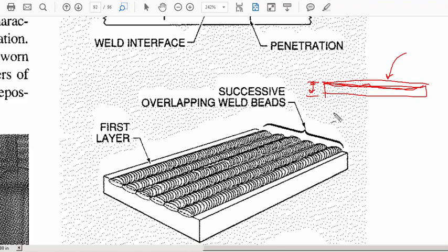This is obviously very abrasion resistant, so if you wanted your part to be well protected, you might do a surface weld. One other interesting feature about surface welds is they don't necessarily have to have the same characteristics as the base metal. So the filler material that's coming on top could slightly be different for one reason or the other. It could have some special properties that you want it to have, since it's going to be a protection application many times. Your filler material could be something very different than the base, just for that protection process, which is what sets it apart from most welding processes.